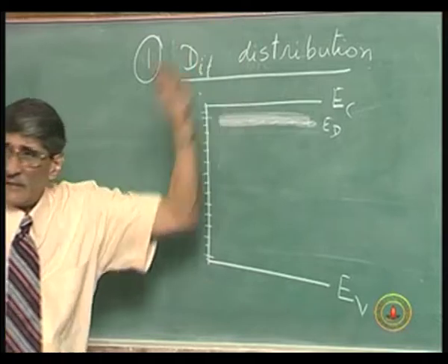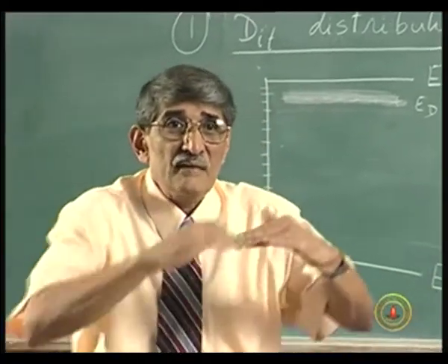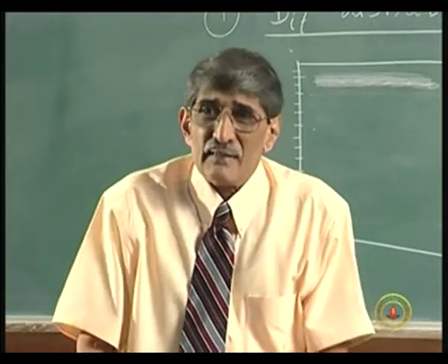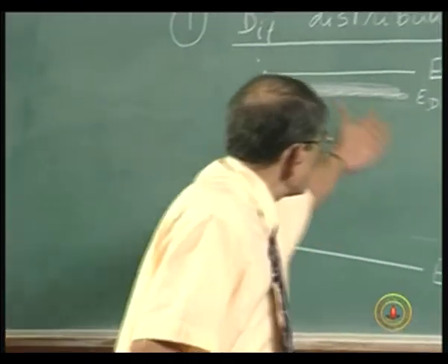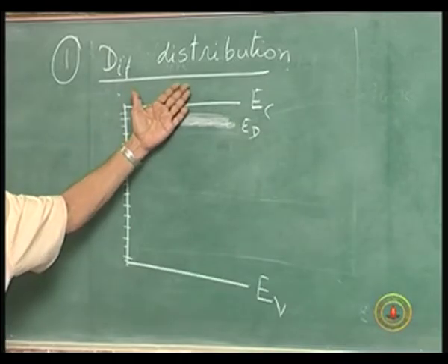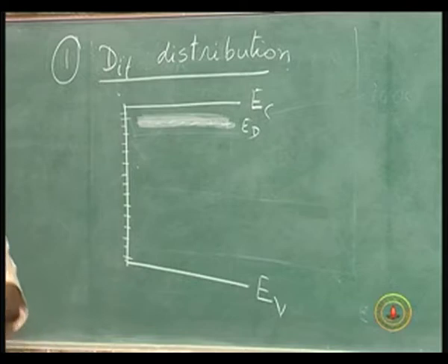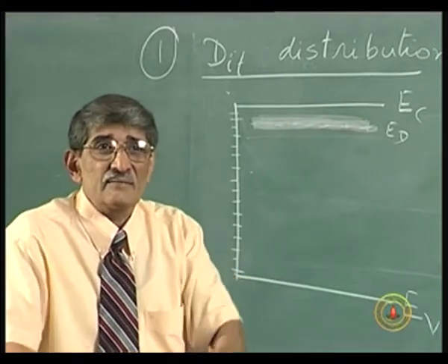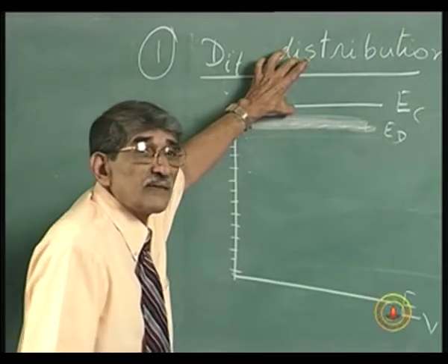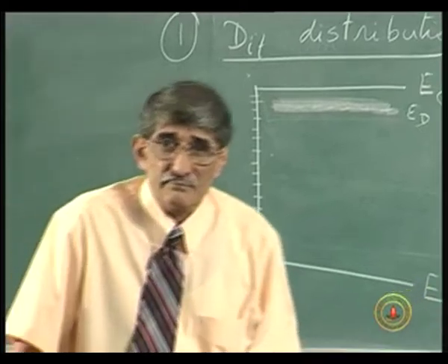It can even merge with the conduction band. That is the situation that you have. So, multiple levels are there. It is just like the energy band formation. How is the energy band formed? How do you get the conduction band? The conduction band is formed because there are silicon atoms which are nearby, the electrons in the outermost shell interact with each other and multiple levels you get. Same thing happens with impurity when the impurity concentration is high.